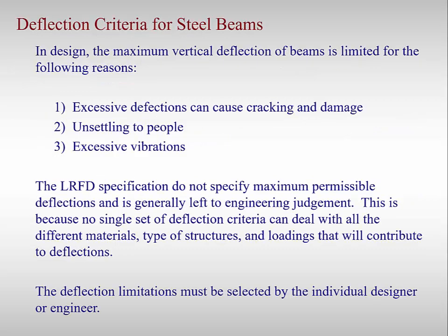When designing beams for floor systems, how much the beams deflect is an important design consideration. Deflections are considered a serviceability limit state. Excessive deflections can result in cracking and damage to components of the building.